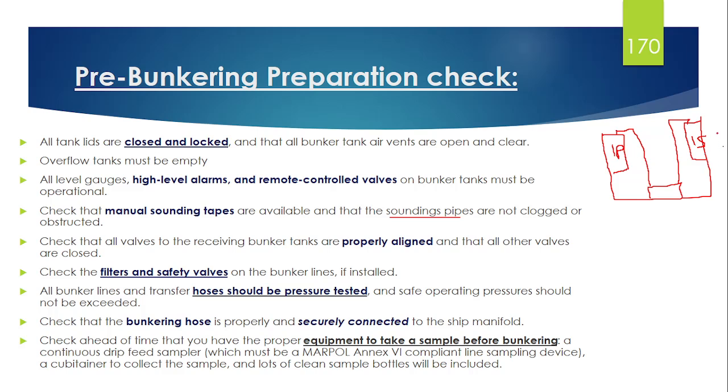After that, also check the sounding of all the other tanks, to ensure that your bunker valve is not leaking, and second, that you are not receiving unnecessary oil in the other tanks, causing unwanted contamination. Because sometimes the bunker valve gives way during the bunker, and you may have bunker contamination. To avoid that, when you start to receive bunker, you not only take the sounding of that tank, you also take the sounding of all the other tanks in which you are not taking bunker, to ensure that there is no contamination.